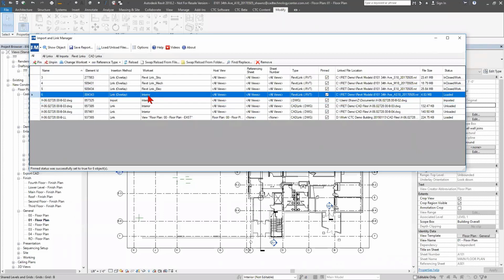One other thing here, I'm noticing something a little squirrely. This Revit link right here, you can usually identify the Revit links pretty quickly because they're numbered. They always number their links. You can also tell over here that the type is a Revit link. But this happens to be an AS18 file. This is an architectural site in Revit 2018. I can tell from the file naming convention right there. This architectural site file, probably linked in for visibility purposes, happens to be on the interior work set.